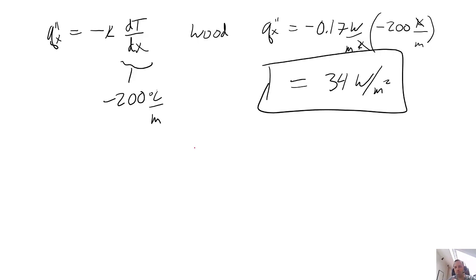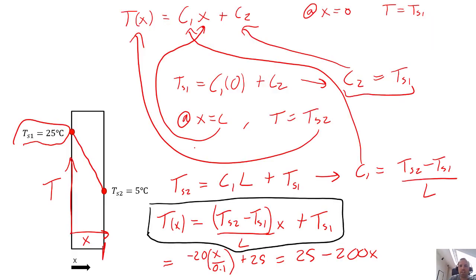Oh, actually, before we move on, notice that we get a positive number. So Q, our flux, is positive. It could be negative. That's totally physically possible. We could have a negative flux, but what does positive flux mean? If we go back to our coordinate system, positive flux means that the flow of heat is in the direction of our coordinate system. So we just see that heat is going from left to right, the same direction as our coordinate system.